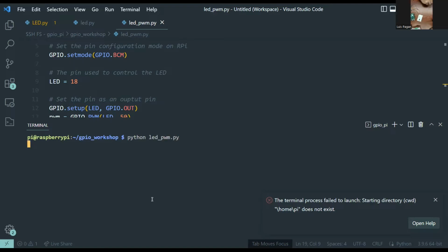So there we go. I don't know how well you'll be able to see this, but the LED is in fact getting brighter. With the 50 Hertz frequency oscillation, you can kind of see the LED actually flickering. Now, if you were to do a higher frequency, this would be less visible. But for the purposes of the servo and the motor control, it doesn't really matter. And I don't expect you guys to put LEDs on your internal comp robots because they serve absolutely no purpose other than being cool.